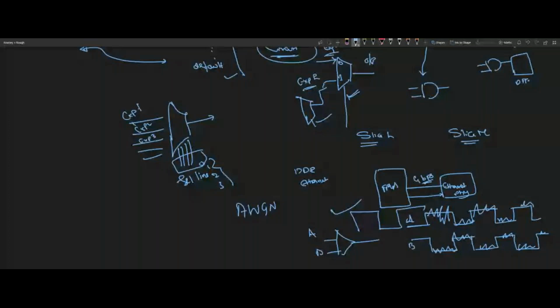and the number of medical equipment may be a few hundreds, right? Whereas if you want to manufacture a mobile, the number of mobiles manufactured will be in millions, correct? So wherever mass production is there, I go for ASIC. But where the numbers are limited, I prefer FPGA. Low volume applications, yes, low volume applications.